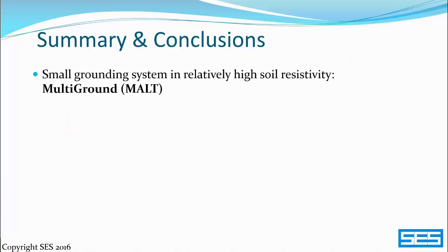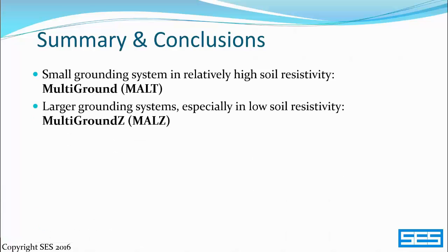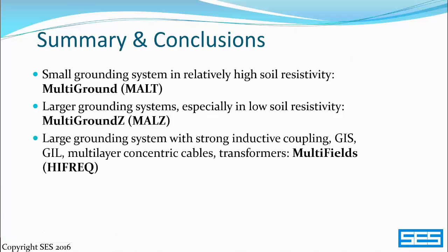So for small grounding systems and moderate to high soil resistivity, one can use the equipotential assumption with the MultiGround software using the MALT grounding module. For larger grounding systems, especially in low soil resistivity, it's imperative to consider the impedance of conductors with the MultiGroundZ software using the MALZ grounding module. And when inductive coupling is substantial and cables need to be modeled accurately, the MultiFields software using the HIFREQ grounding module is best. Note that HIFREQ can also include transformers in the model.